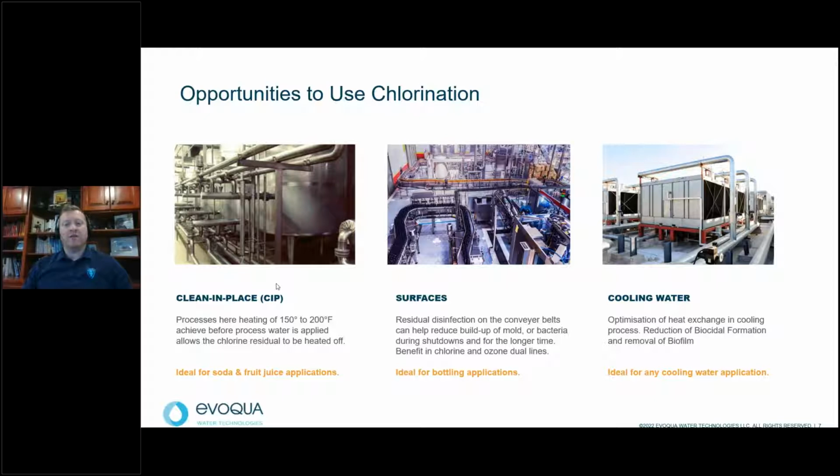It is also ideal in cooling water applications. Chlorination disinfection effectively removes biofilms from water networks and prevents their formation when continuously dosed. Chlorine is not only effective at killing the biofilm, but some studies have also shown great success of chlorine-based treatment in detaching the biofilms, promoting the significance of disinfection in an environment where biofilm is a hazard to the overall process. So again, this will be applicable to any of the cooling applications that may be throughout a beverage facility.